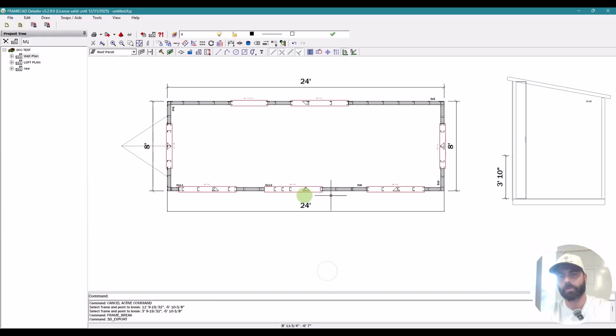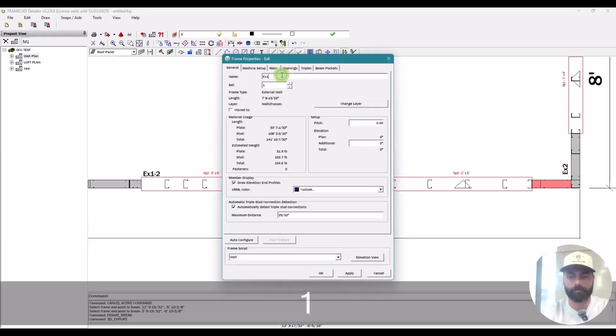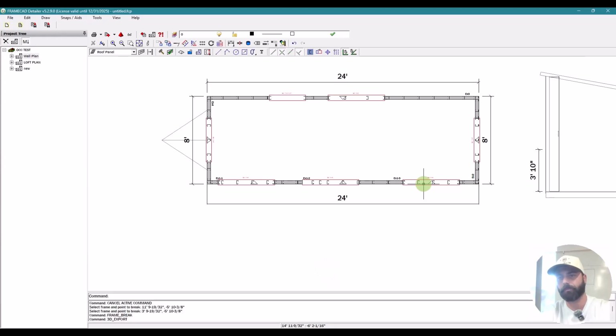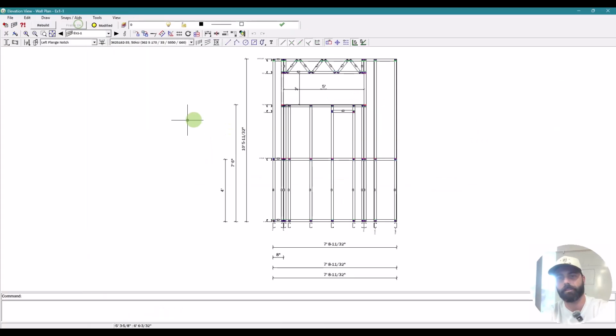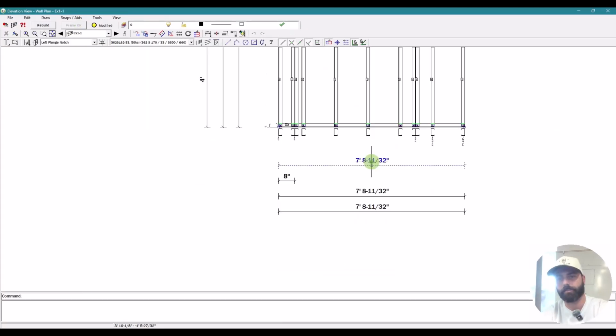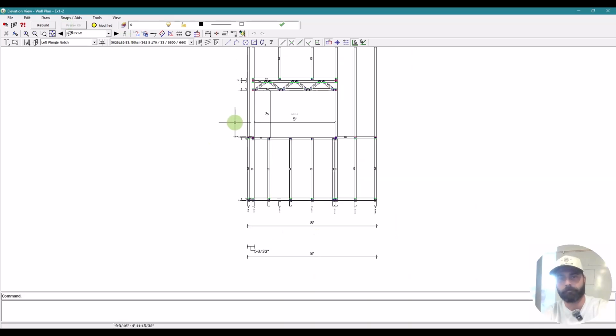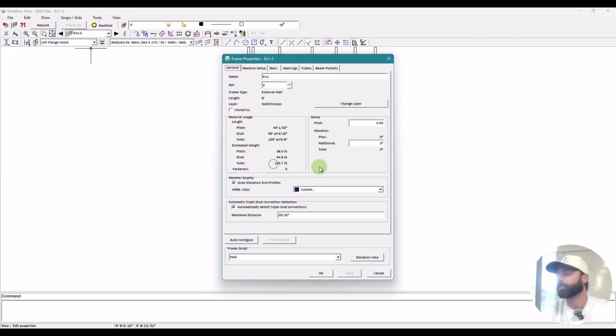And now you have panels that you're moving around that are 130 pounds, not that 360 that we were originally looking at in the very beginning. So a little bit easier. The only thing we were missing was these horizontal and vertical service holes. I'm not going to reset the values, but make sure you guys put service holes in the framing for sure. We'll stop these short so they don't go through the header.